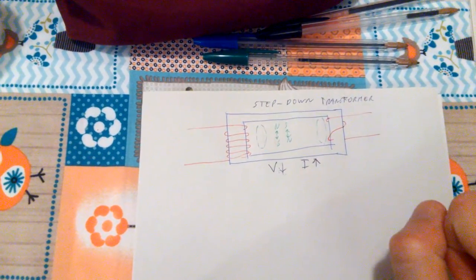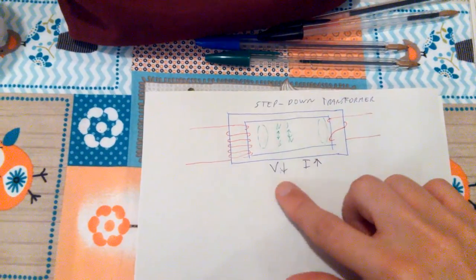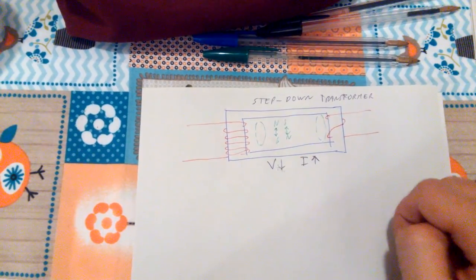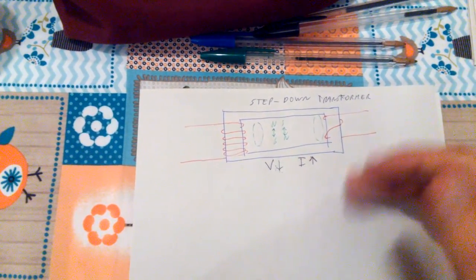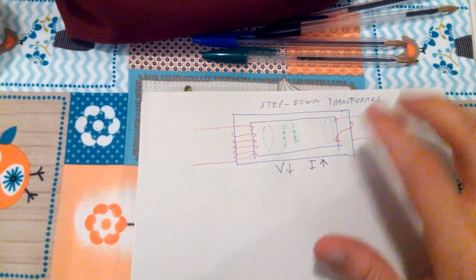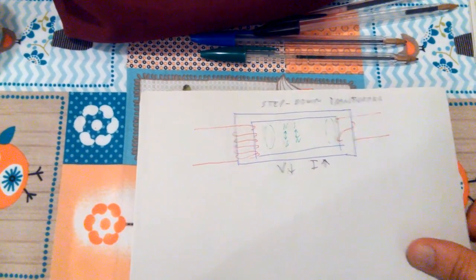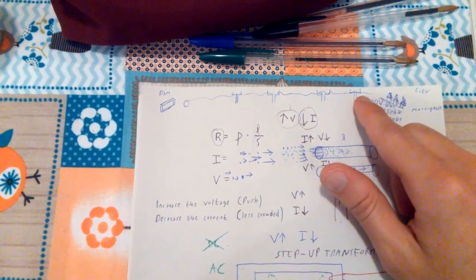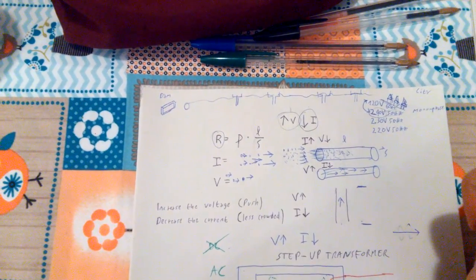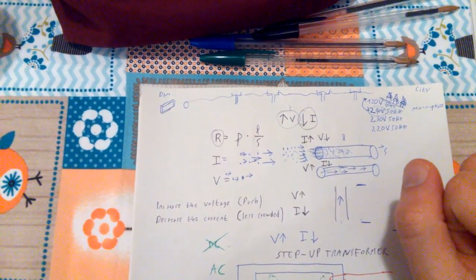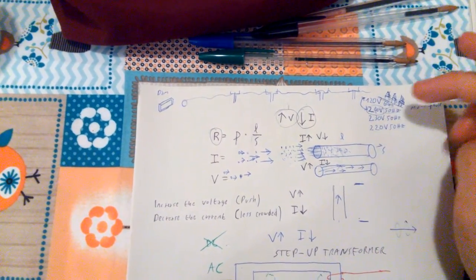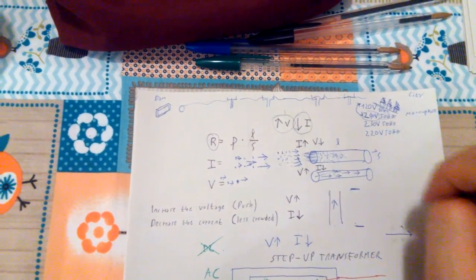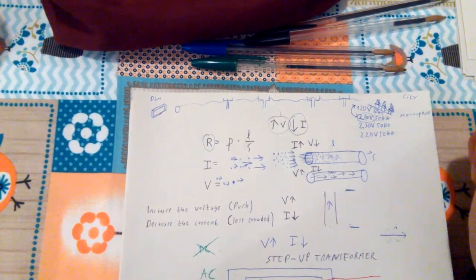And this is necessary because the voltage has to go down, because we no longer have to carry it through long wires to get to the city. We are in the city, basically. So we had to lower the voltage for safety reasons. Now that we have lowered the voltage, we are just gonna get one of the three phases, and we're basically gonna use that for the single household. So each household only receives one phase.